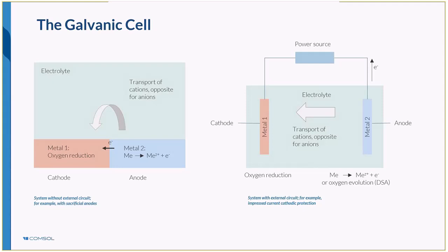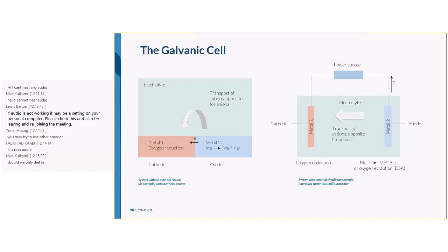On a micro scale, we might model this as diffusive transport of the ions to determine how the concentration influences the local conductivity. On a macro scale, we might assume a uniform conductivity and use Ohm's law to represent the passage of charge in the electrolyte. The corrosion module offers a number of different levels of model complexity, which allow you to customize your model to incorporate the necessary level of detail and accuracy for your system.